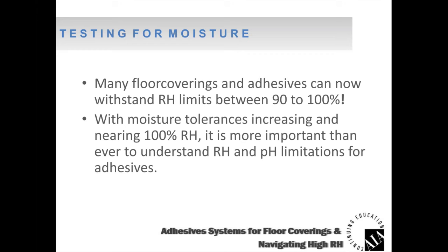Many floor coverings and adhesives today can withstand very high RH limits, mid 90s, high 90s. There's some floor coverings that actually go to 100%. With moisture tolerances increasing, it's even more important in the present day to understand pH as it relates to this very high RH. So that's something that we're going to spend some time on here today, because I want you all to understand pH, because with these high RHs being allowable, it's just more critical to understand pH, and we're going to explain why.